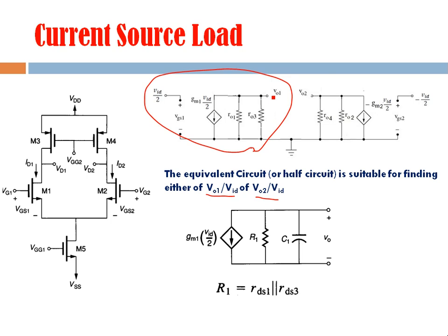And you can see that we have selected this part. It means this output and ground, right? So whatever capacitive components are connected between this terminal and ground, those components will be represented by this C1, and C1 will be given like this. So you can see here in C1, the first component is CGD1. CGD1 is the gate drain capacitance of the first device. This is gate, this is drain. It means we are talking about a capacitive component which is connected between this gate and drain. So this is this CGD1, right? I am mentioning here 1. This is our first component.